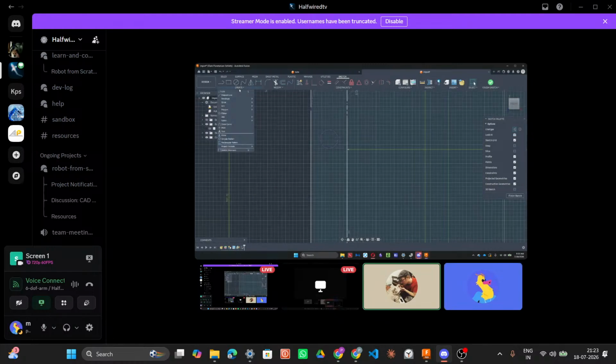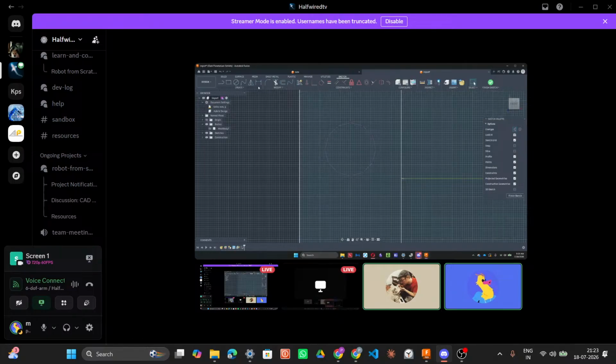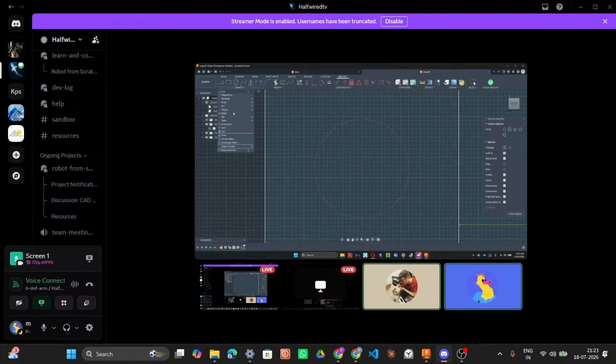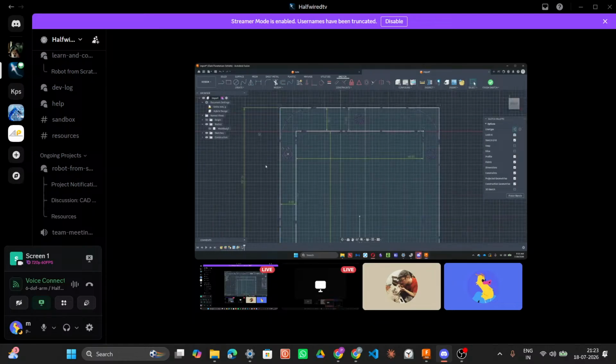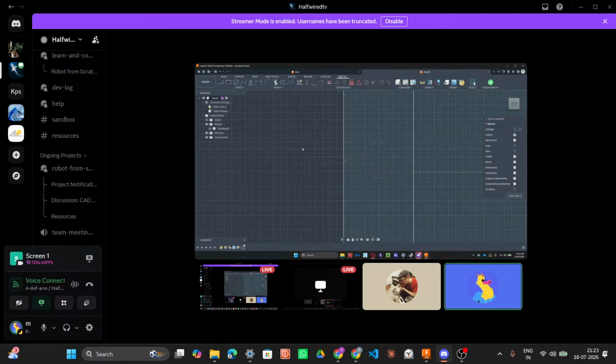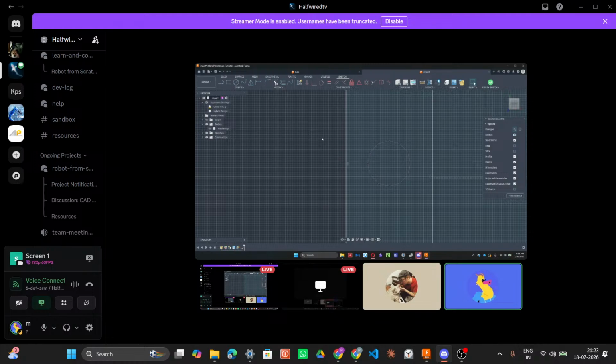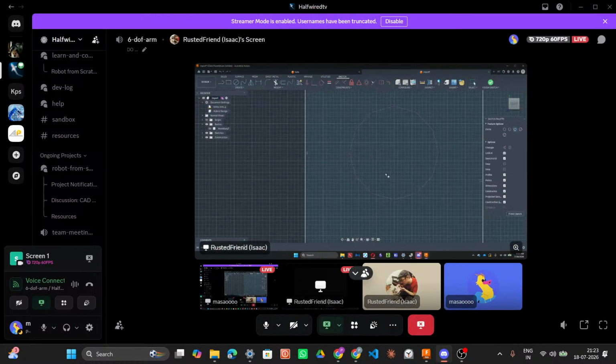And then, since these aren't defined as circles, I can say a 3-point circle, or I'll probably do a 3 tangent circle on here, here, and here. And I keep forgetting, I just eyeballed the thing when I created it in that spinning thing.